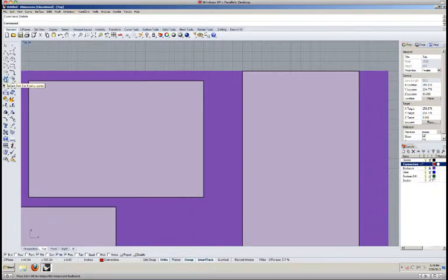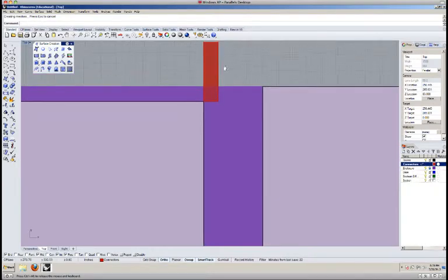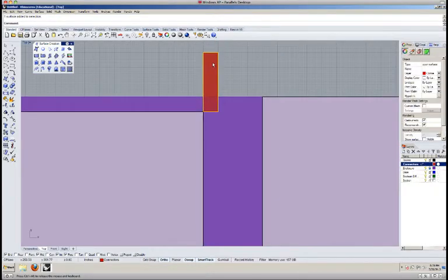And I'm going to use the surface planes again. So I'm going to grab this guy, put it over here on the side, just because I want to be able to quickly select this rectangular planes option. And I'm going to draw one stair tread. I know that the treads are always going to be the same for the most part. So I'm going to click a point, type in 12 and 48. So it's going to be 12 inches deep and 48 inches wide, or 1 foot deep and 4 feet wide.